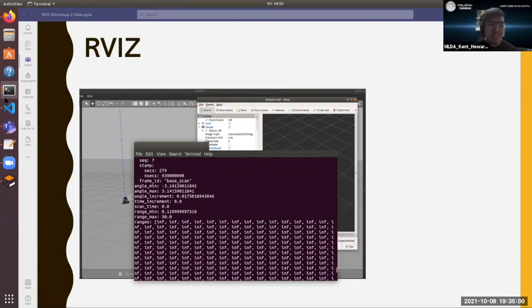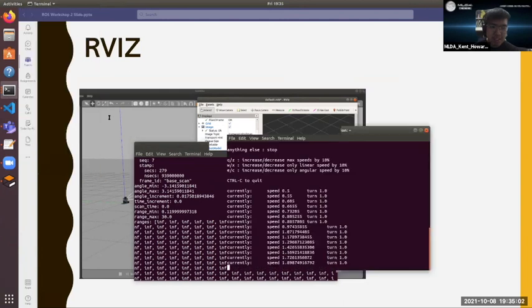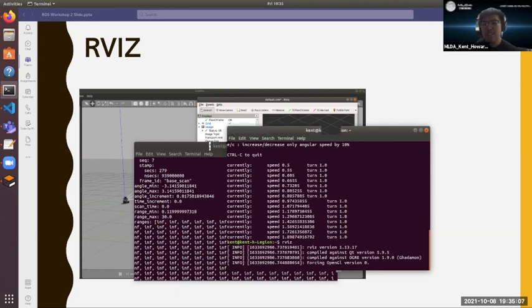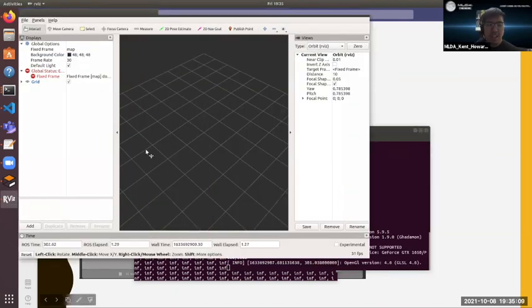So ROS has a tool called RViz. Let me demonstrate it. All I have to do to run it is type rviz. And this is RViz. Here we have the first option that we're going to need to work with, the global option. This fixed frame refers to one frame that you declare as the anchor point of all the visualization you have here.